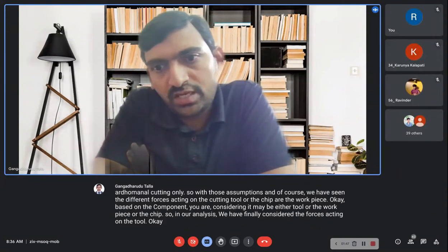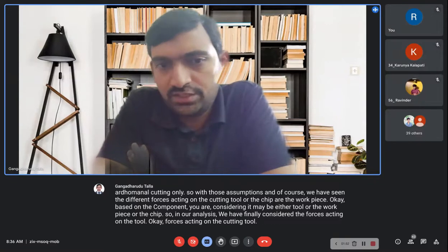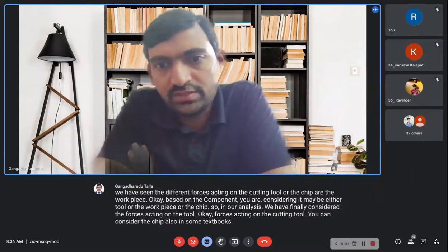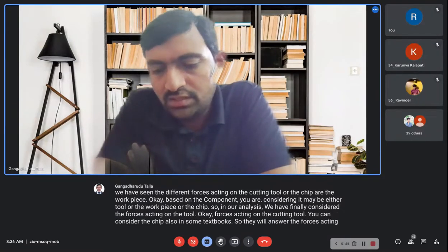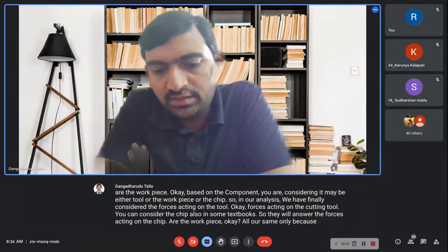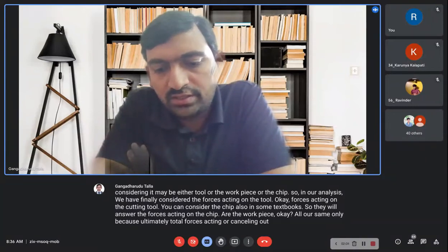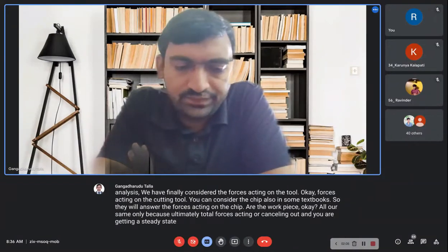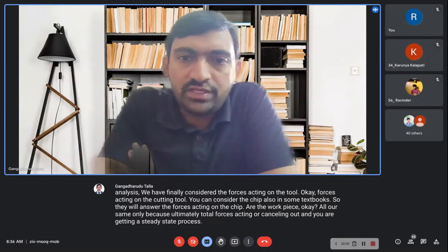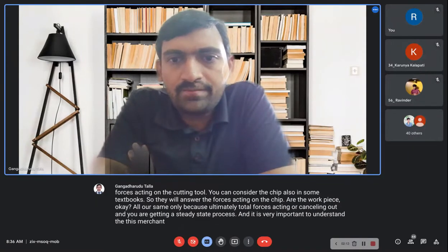You can consider the chip also. In some textbooks, they will consider the forces acting on the chip or the workpiece. Okay, all are same only, because ultimately total forces acting are cancelling out and you are getting a steady state process. And it is very important to understand this Merchant theory.